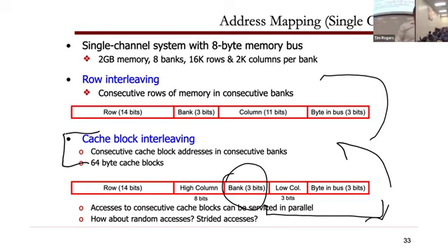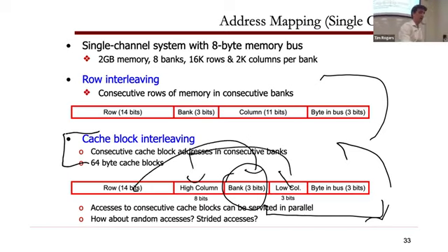Now, I could have put the rows here instead. I could stride the rows first instead of the columns, but this is dumb, right? Because now the fast changing bits are going to change rows and you're going to have to do RASes to light up the other rows. So rows always come last because those are the slowest changing bits. And that's the expensive thing. Every time I change a row, I have to pay a cost. So I keep the columns low and then stick the bank bits in where I need them. Yeah. Yes. So then, yeah.